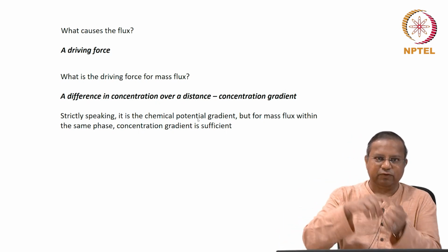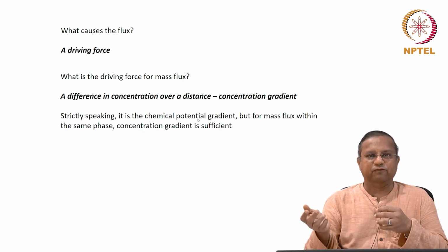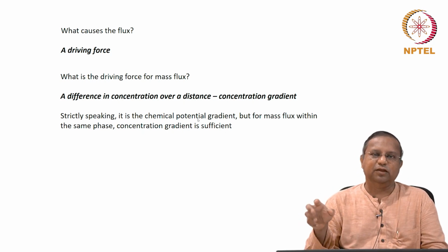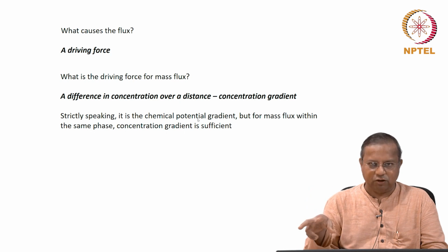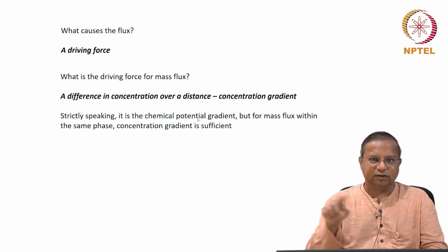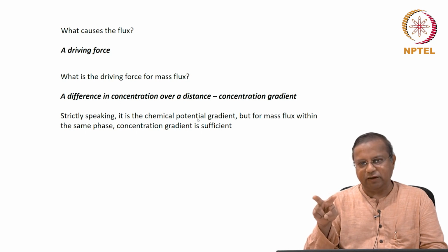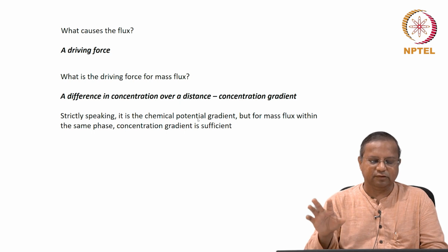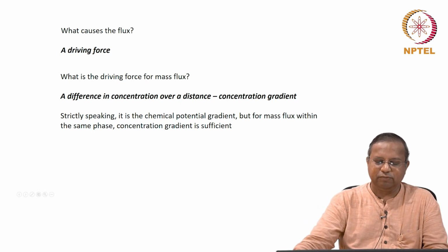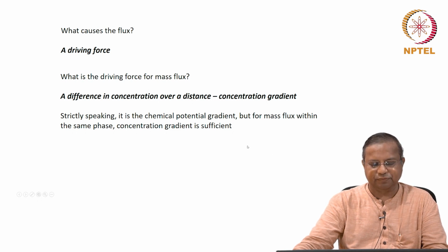However, if you go from a liquid phase to a gas phase or from a gas phase to a liquid phase, across phases, interphase transport, then the picture becomes very different. You cannot use concentrations. You know the reason from thermodynamics. It is only the equality in chemical potential that determines equilibrium, if you recall your thermodynamics. Okay. So, the difference in chemical potential is the actual driving force, but we do not have to be so strict because concentration works especially within the same phase.